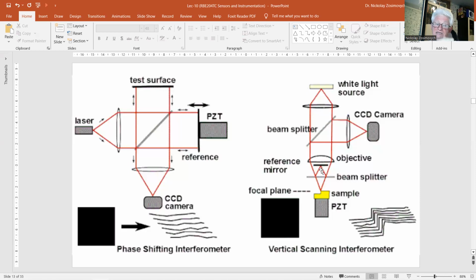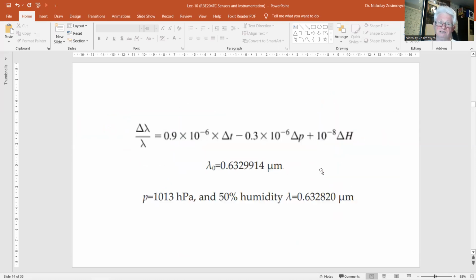So an interferometer, therefore, needs a very stable source to minimize phase noise in the output signal. Altogether, an interferometer is quite an expensive instrument. The range of an interferometer runs from several centimeters up to several tens of meters and depends on the maximal number of subsequent fringes, light-dark transitions, that can be counted.